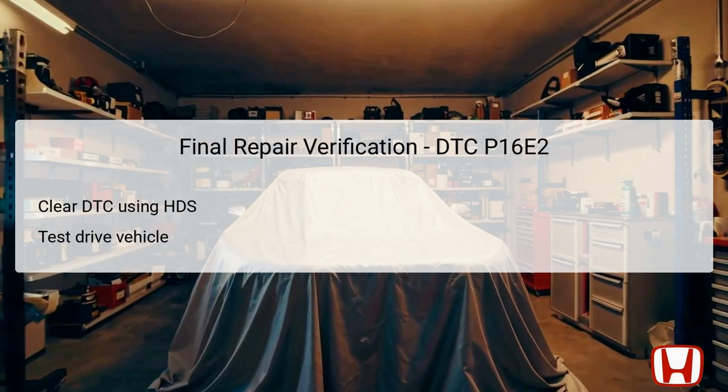Following the code clearance, it is essential to perform a test drive of the vehicle to assess if the problem reoccurs. During the drive, pay attention to any warning lights and monitor the vehicle's performance to see if it operates within normal parameters. If no issues arise post-test drive, it suggests a successful resolution of the initial problem.